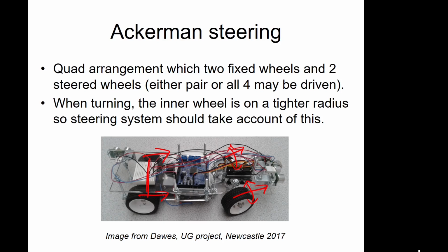etc. So you do get less maneuverability, but what that does lead to is better traction to the road. So for example, you can go around a bend a lot quicker on an Ackermann steered type of system than you can on an omnidirectional type of system, which will tend to slide sideways. Okay, so there's benefits and trade-offs for the type of geometry you use. But this would be your typical geometry for a car, for example.